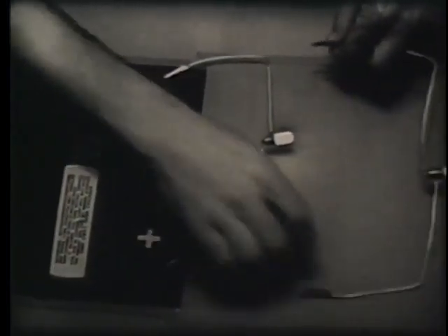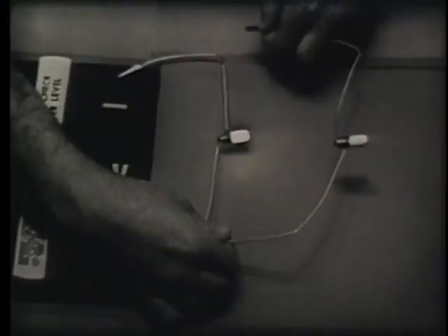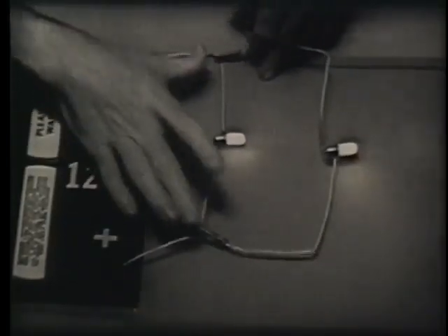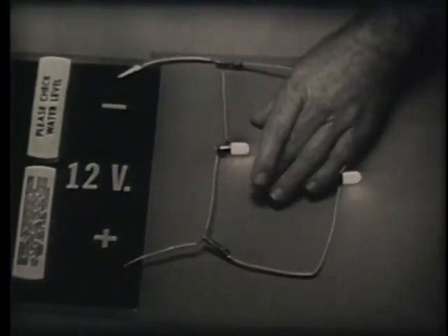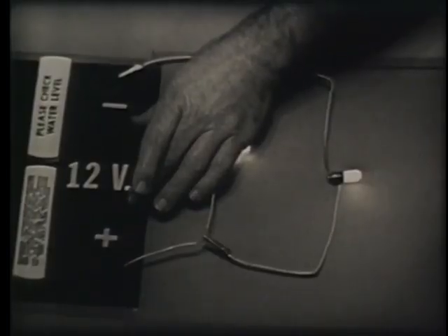Now, since the applied voltage is felt across this bulb, I should be able to connect this one like this and still have the applied voltage across it. And you can see that it's starting to look like a parallel circuit. Now, we could add a third branch, a fourth branch, and on and on. Each branch would still have the total applied voltage. Now, this fact is supported by Kirchhoff's voltage law, which states, in effect, that the applied voltage is dropped around each closed loop.